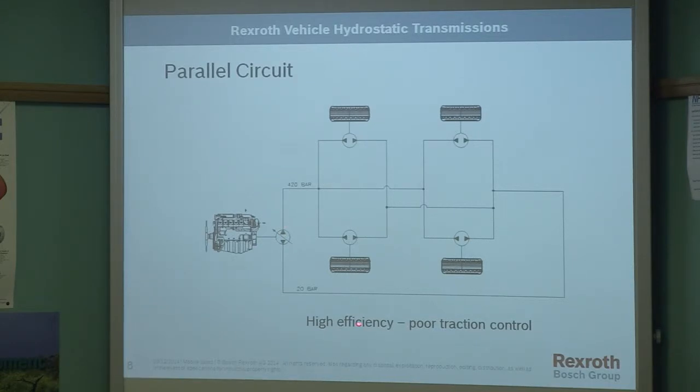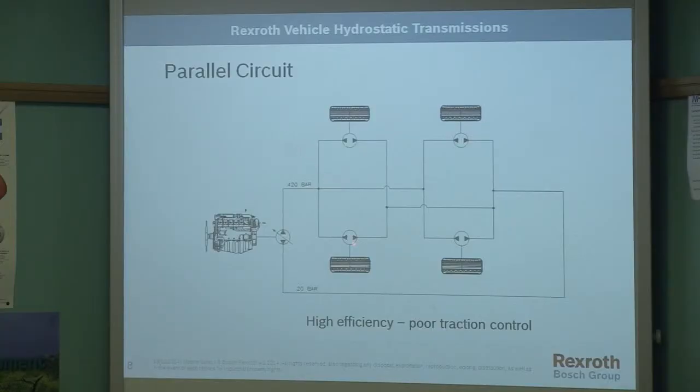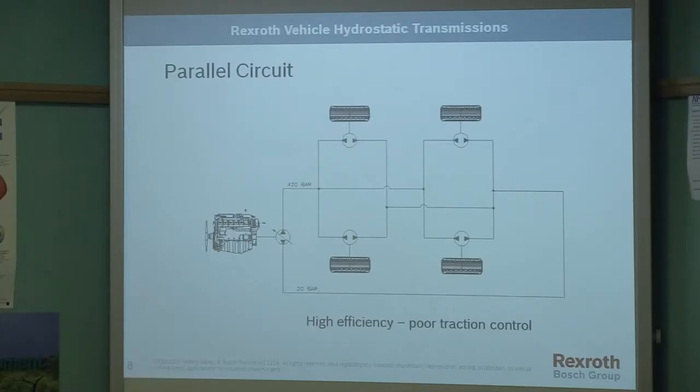This is quite a high efficiency system, but it's got poor traction control, because you can see if all these motors are in parallel, if one loses traction, it can effectively take all the flow from the pump. And it's not unknown for somebody to overspeed one of these units and burn the motor out. So this is a parallel circuit, high efficiency, poor traction.